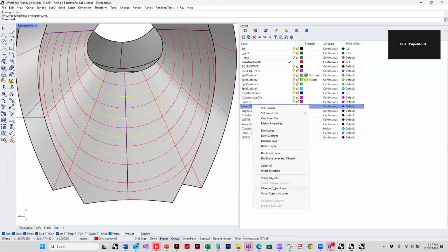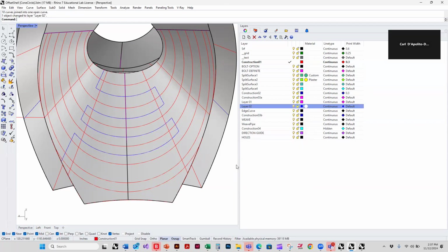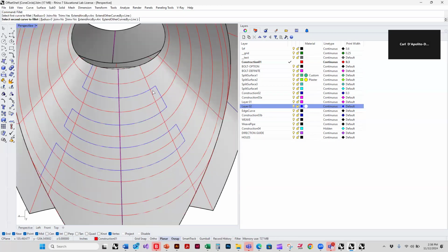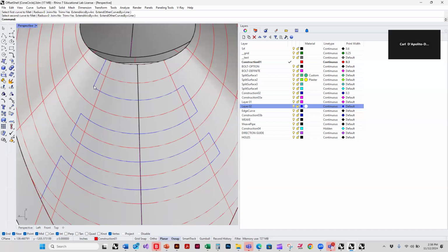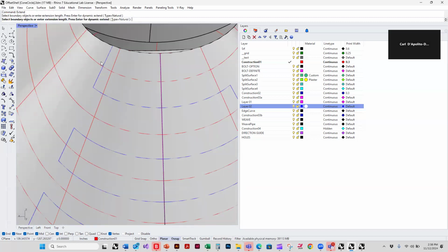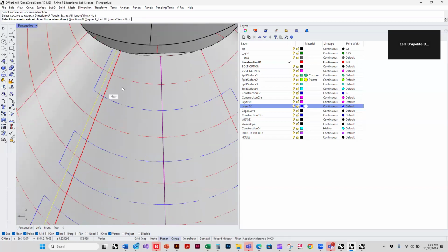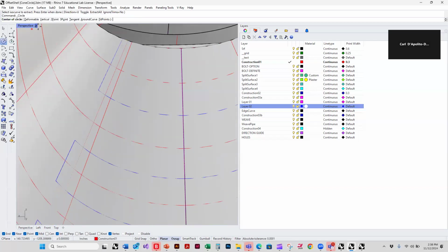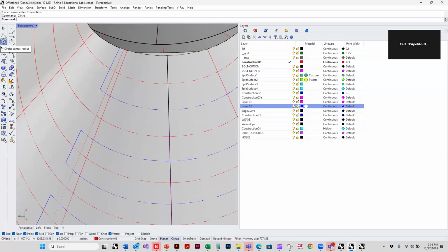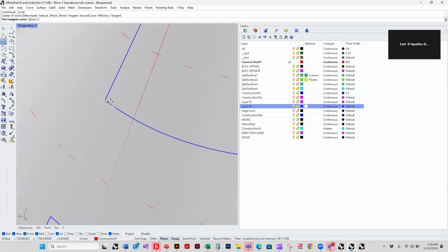And because this is routed, I needed to put a radius on the corners, which is difficult because these are 3D curves, so they won't fillet. I can't just fillet them, probably. And so in order to do it, what I did is, Rhino often can't fillet, but it can find a radius in this manner. If you give yourself a guide curve, and then you do a circle tangent.